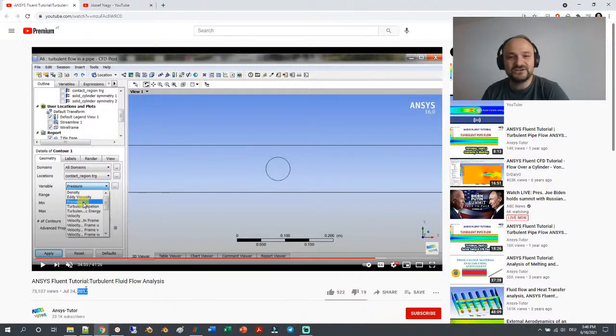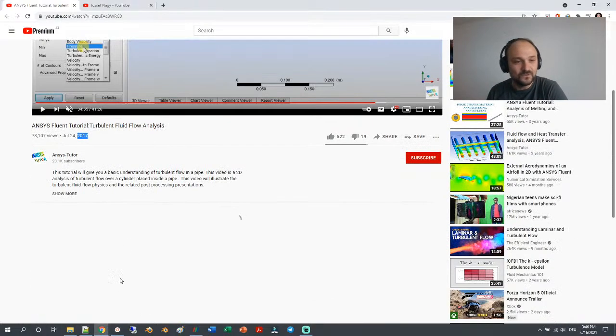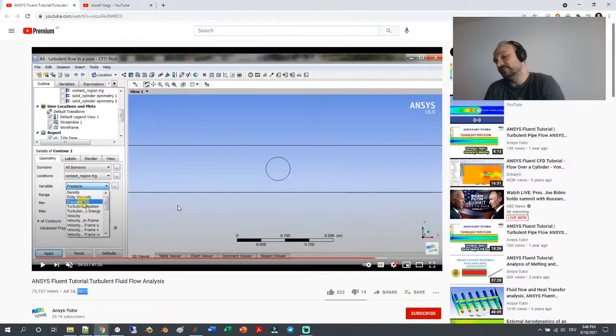There are small changes. Maybe if we had access to the mesh, then we would get the same results here. So feel free to download this tutorial, play around with it, change the mesh, and then run it. So this was it that I wanted to show you. We successfully set up the case and ran the case. It was not very difficult, so you can do it very easily. Just start with the entries in 0, then constant and system, and it is just a straightforward setup.